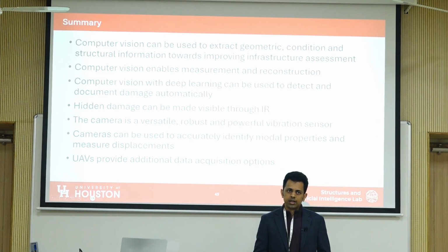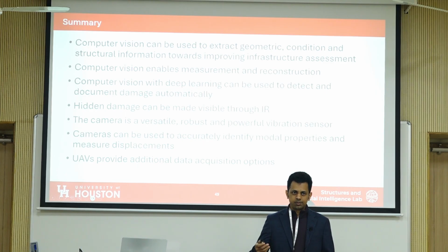Also a good question. For cracks that are deep in concrete, for example, there's not that much of a strong thermal signal that sort of crack might result in at the surface. But that being said, if it's a very big crack, or if there's a hole, say through some water ingress that is making its way through, then that's probably the kind of thing that you will be able to see with the thermal camera.